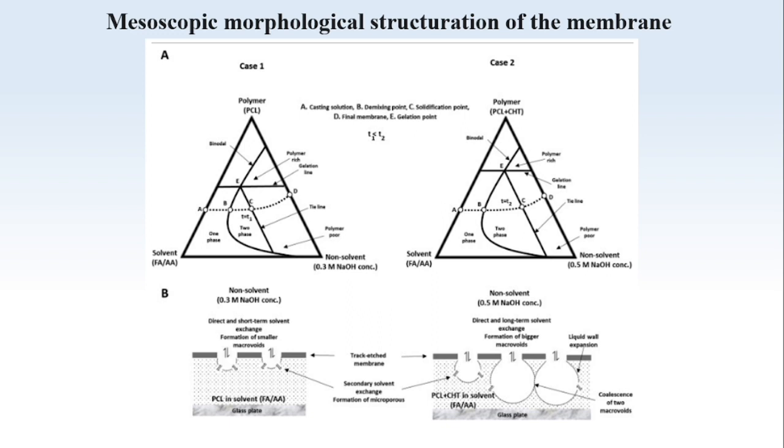The presence of the skin layer on the membrane edge restricts the non-solvent excess, initiating a heterogeneous solvent-non-solvent exchange, resulting in macrovoid formation. The polymer composition, polymer weight percent, and non-solvent concentrations influence the macrovoid size and membrane porosity.